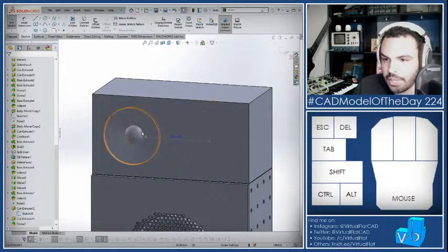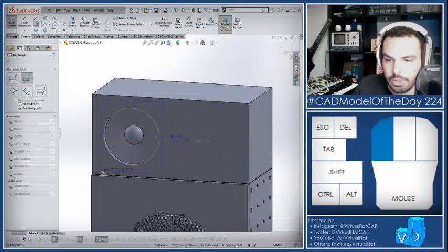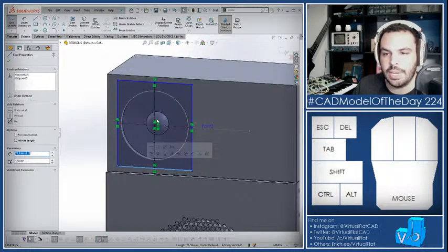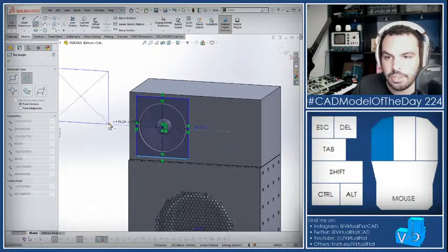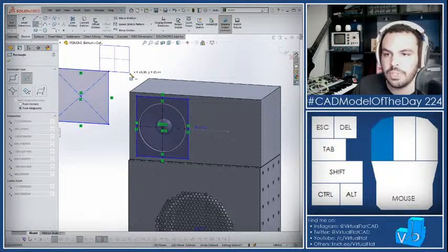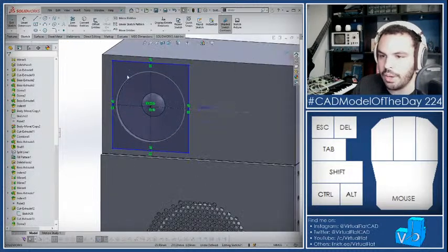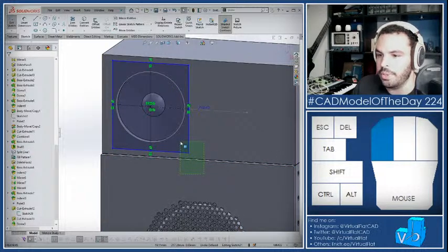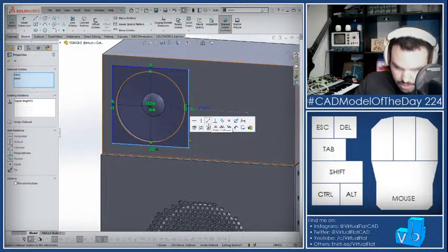So let me show that sketch. Yeah, I think I'll do another sketch-driven pattern. Like that. Oh, another tip that I like to tell people. I don't know when this was added, but for the center point rectangles, usually you'll see them stretch from the centers, from the corners. You can actually say from midpoints and do it like that. And the reason I like to put it on midpoints is that if I need a square, I can just do my center rectangle, click out here and swipe, get a right to left box. I grab the two legs and I can say make equal. Makes a really quick square.